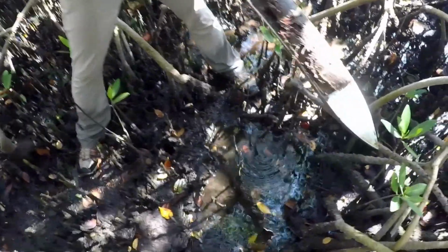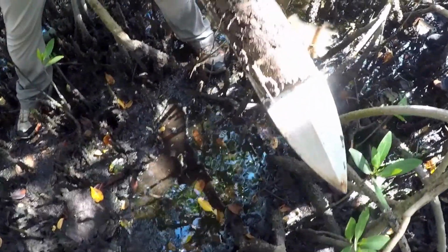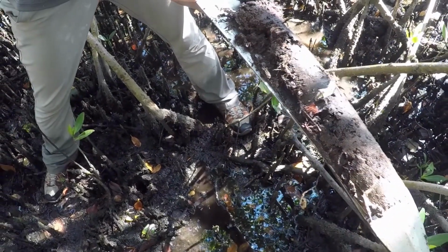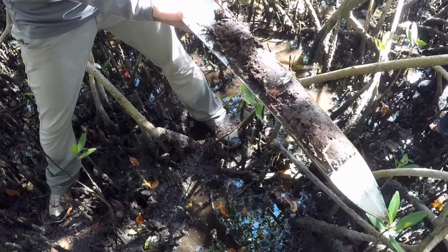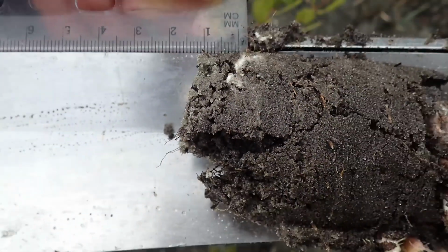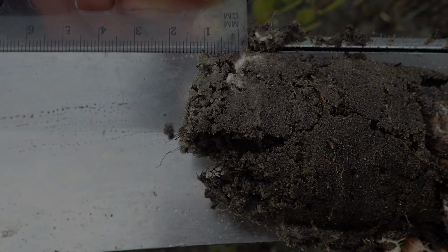Record the amount of soil deposition as the average of 4 measurements from the top of the feldspar layer to the surface of soil. Make note of the location where coring occurred, then replace the sediment core. Avoid coring in repeat locations and at locations with visible bioturbation.